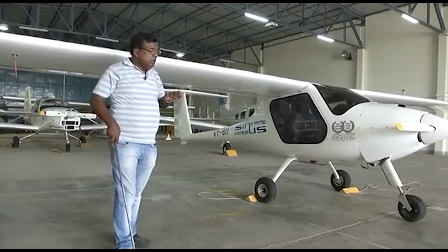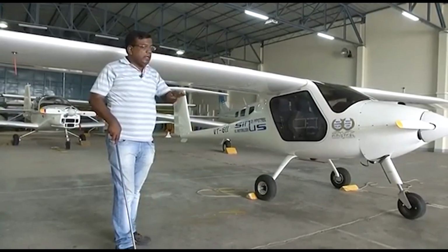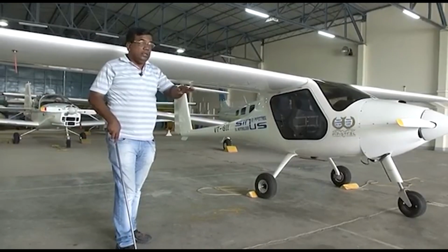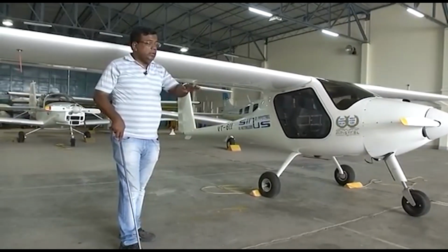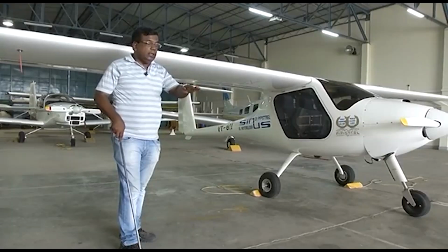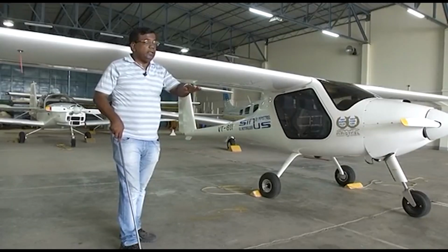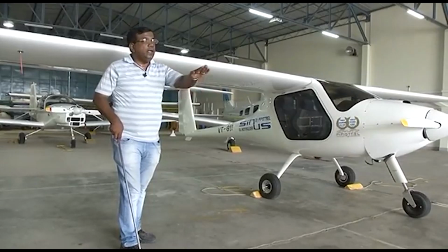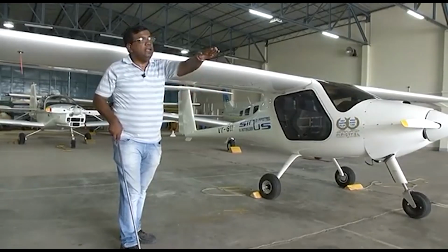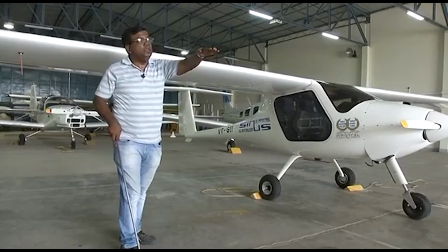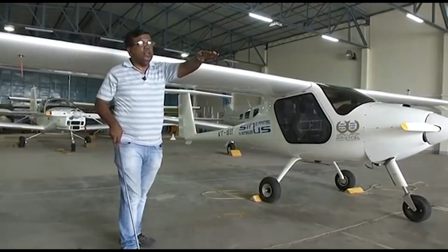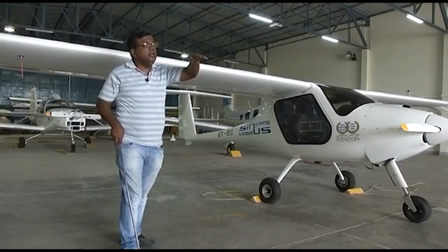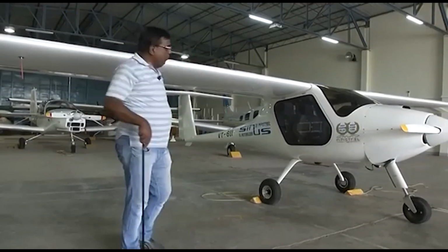Okay? So once I am going like this, I have started the engine, got a particular speed through acceleration, and then I will pull the elevator, and elevator will go up. That will make the aircraft roll slightly like this, and then continues flying, climbing, and after that again I make the neutral position of the elevator or to a desired elevator position. Basically I am now reducing the elevator angle and I maintain a cruise.